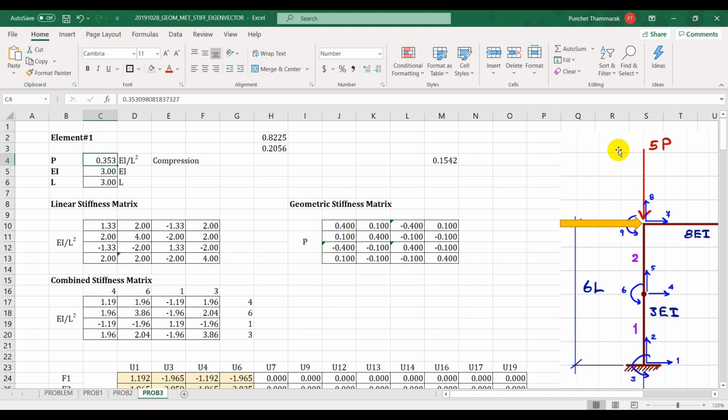And then at one point, the slope just changes, it reduces. So that is the softening effect. You have the reduction of slope. And then at one point, as you keep running the analysis, you find that the deformation is really, really large. And that moment is the point where we define the structure to be under buckling failure.